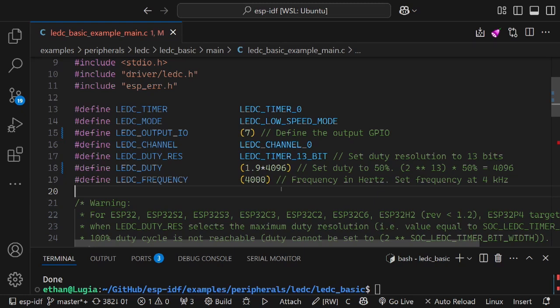Good stuff. Okay, question? What if we set it to a very high number? Would the LED burn out? Sure. The whole point of PWM is that it's just voltage low and voltage high. The LED will never burn out because the maximum current we're putting through it is the actual rated current for the LED. We are unable to increase the duty cycle past 100%, because at that point it would just be feeding in the maximum allowed current at all times, as opposed to the maximum allowed current for just a short period.